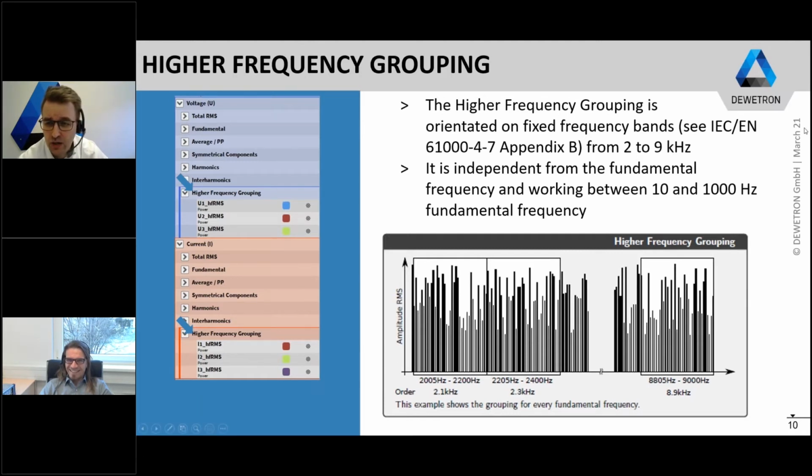The question would be, how do you group for DC components? I think DC components are in harmonics in the 0 bin. Is it true? Exactly. The DC component of the signal is contained in the very first value, which is written to the harmonics channel and also to the interharmonics channel. Okay, perfect. That's, I think, the 0 bin, if I'm not mistaken. Yes, right. Perfect. Okay. And so far so good for harmonics, and we are not at the end.